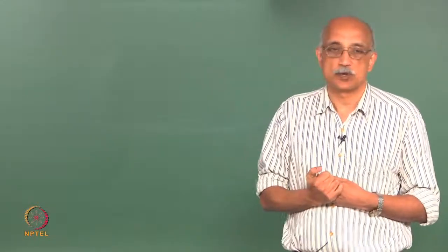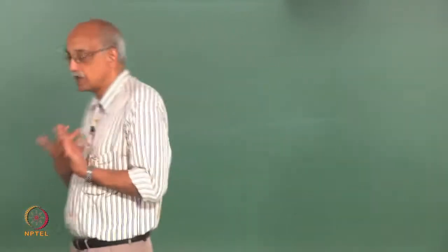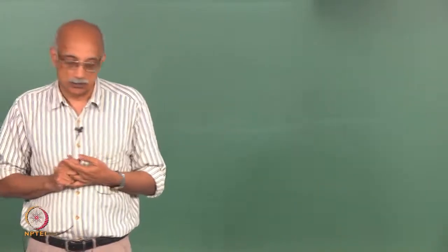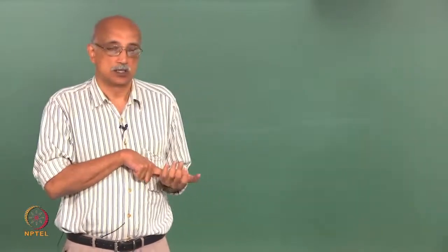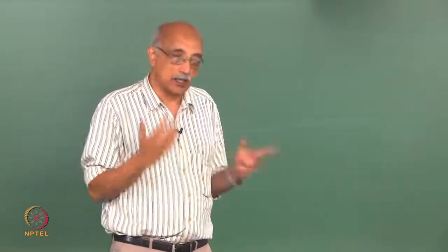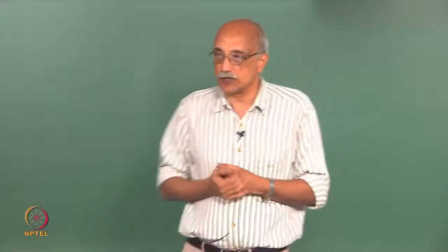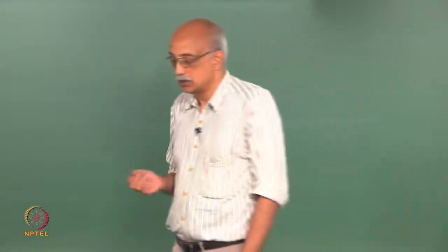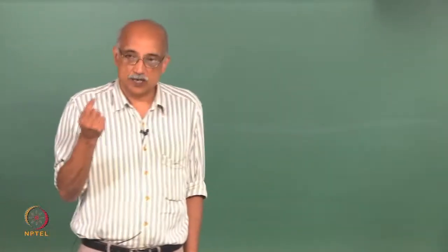Cohesion. If your feed is such that the particles are agglomerating with each other, clearly that is going to impact their screening efficiency. Or adhesion. If instead of passing through the apertures, the particles stick to the sides of the wire, or to the sides of the feeding mechanism, whatever it is, whether it is gravity fed or other ways, again screening is not going to be perfect. There is something called a near mesh size.